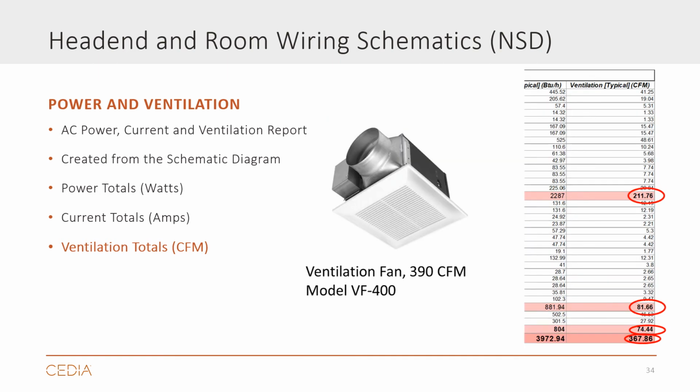So, with a 368 CFM requirement, this is one of the choices of ceiling exhaust fans that we can use to serve the purpose. Again, provided there's enough 75-degree air outside the racks. It can be mounted in the rack room ceiling to exhaust the heated rack air into a return duct or other separate space. And a thermostat can be installed within the rack to start the fan when 85 degrees Fahrenheit is reached.